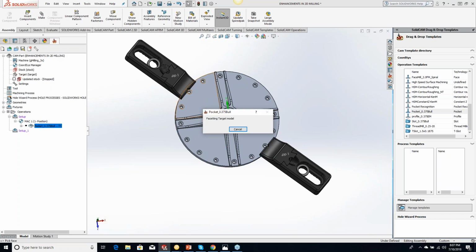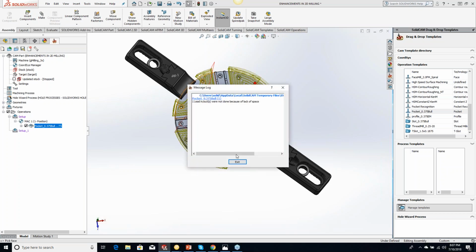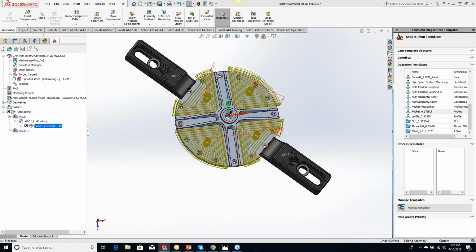And now I'm able to take that pocket operation and distribute it through the entire template, and distribute it through multiple different faces now as well. So that's something that Sydney just added in there for you guys. I think by popular request, a couple of people were asking about it. So that is a real cool thing now. Now you'll see that it's automatically going around my vices. Well, let's take a peek and see what we've done in here.